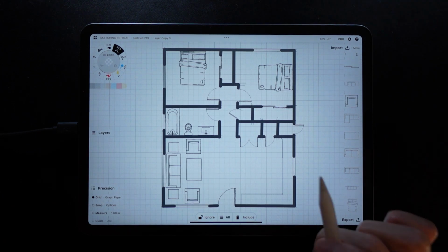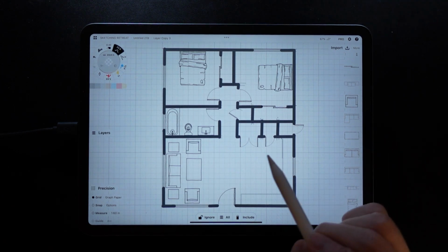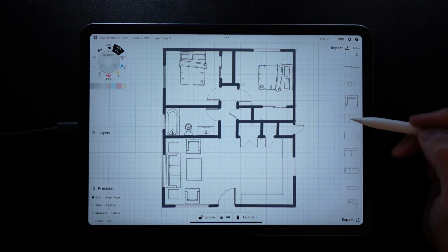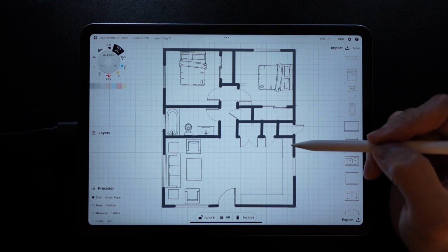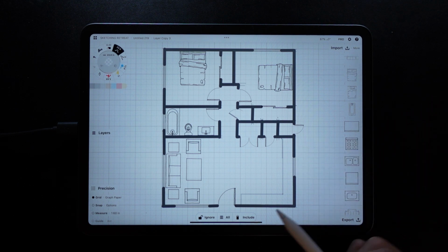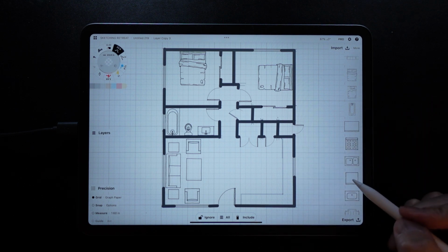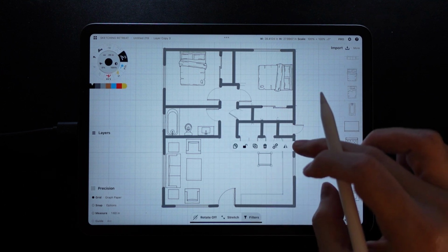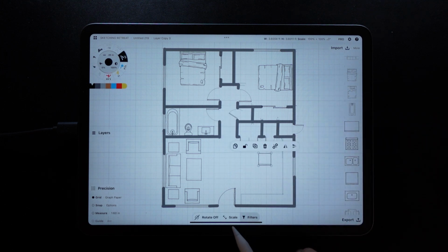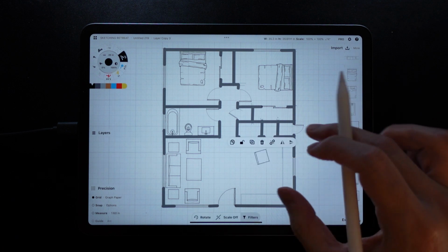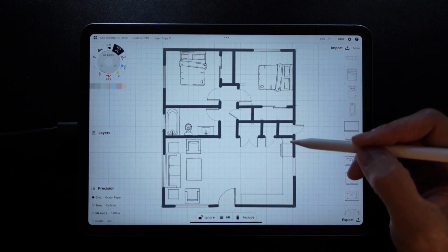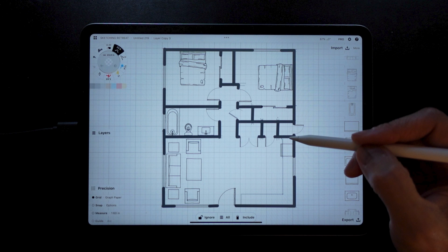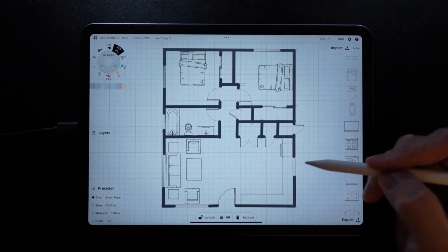And now we're gonna start our kitchen design, and since we have our pantry right here, we're gonna go ahead and look for our fridge. Alright, so probably our fridge could go here, our sink here, and our range right here. Alright, so this is the fridge. I'm just gonna rotate it. Okay, and it's gonna go right here. Just remember to provide at least 15 inches between wall and fridge, so it's gonna be more comfortable to open the door.